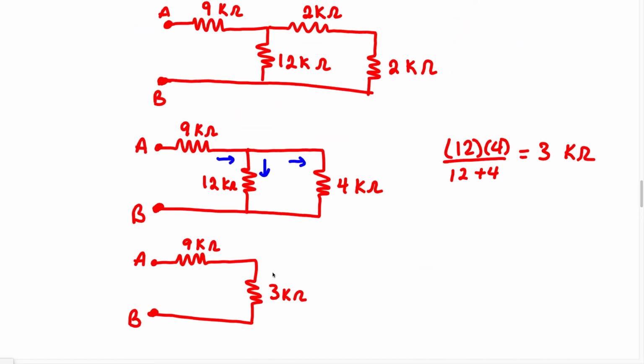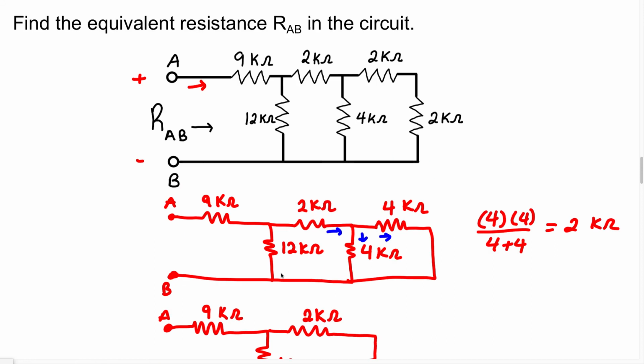So this is how you solve these types of problems. It's a lot of redrawing, that's for sure, right? You have to be able to redraw these problems. So it takes some time, but it's not a hard concept all in all. You just must be able to understand when resistors are in series and when resistors are in parallel.